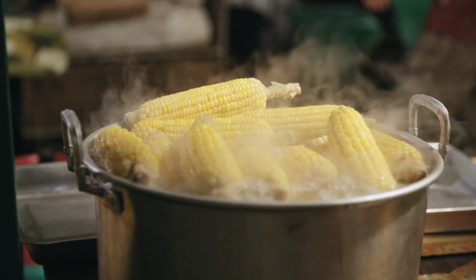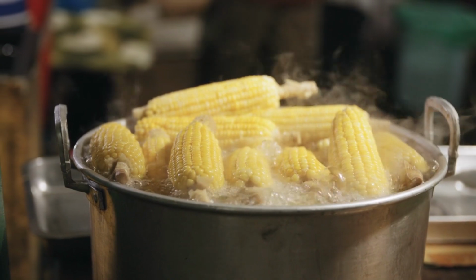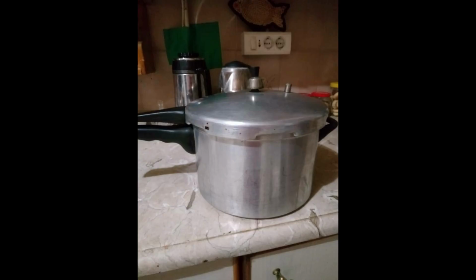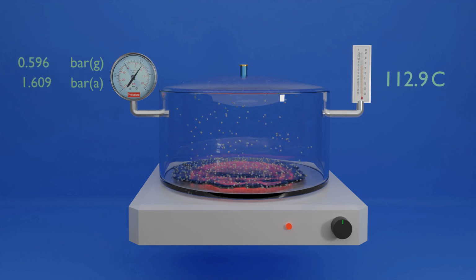When cooking food, we want a high temperature, and since most of the cooking processes take place inside a container filled with water, and since we are always under the control of atmospheric pressure, the water will reach 100 degrees Celsius at the maximum. In the case of a pressure cooker, the lid is tightly closed, so the pressure will increase and the temperature will rise with it, which is what we want, but if the pressure rises too much, the pot will explode. Therefore, there must be control over this process, so that we raise the temperature without causing any harm, and this is the role of the steam valve.